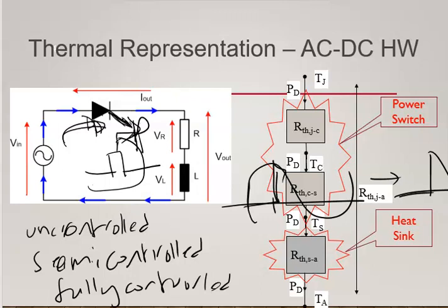So it just conducts over here. If you trigger here, the conduction will start here. If you trigger here, the conduction will only start here. So this is called semi-control. You can control where to switch on, but it will switch off based on the reverse bias of the current. Once reversed, it will cut off. It will start only during your alpha triggering. Okay, this is so-called semi-control.